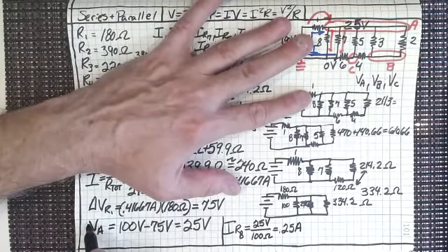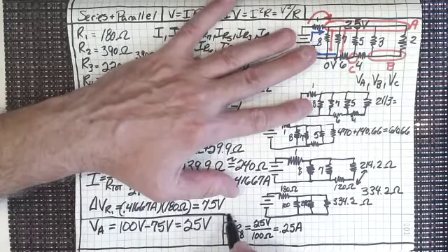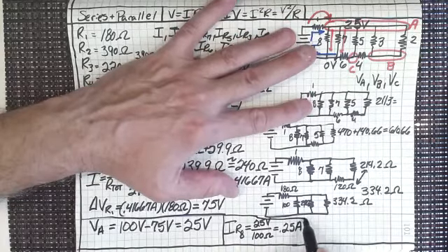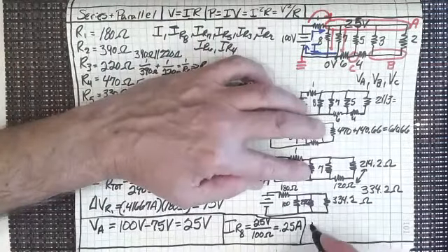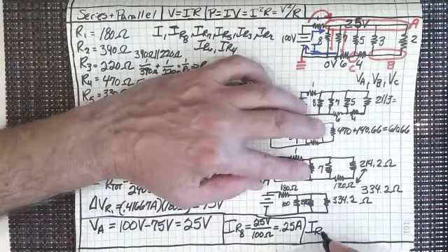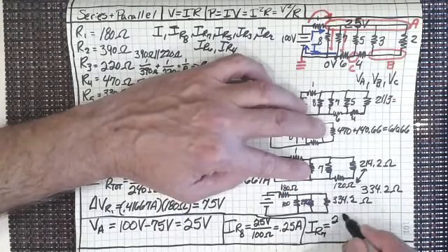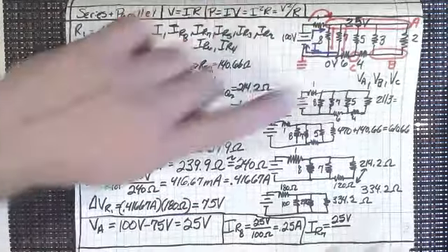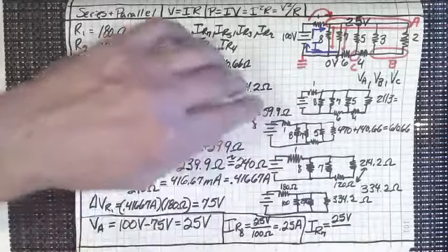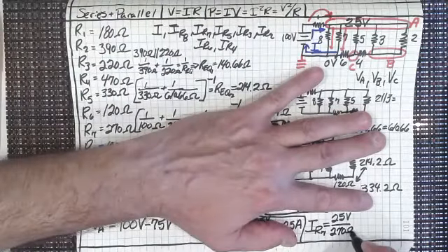We've got voltage at A too. How about the other one, the current that's flowing through R7? Couldn't we do the same thing with that? Isn't that also 25 volts? Except instead, number 7 is 270 ohms, isn't it? 270 ohms.